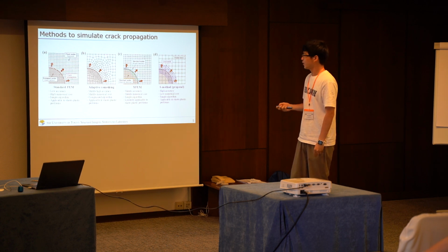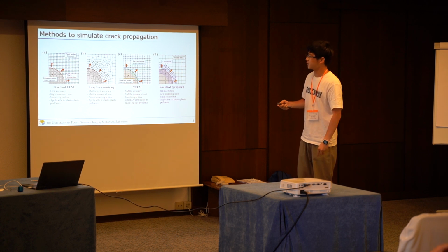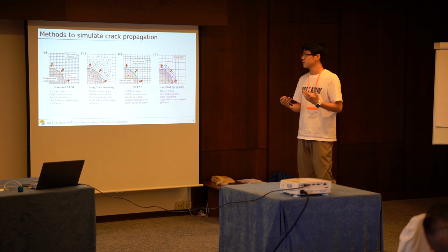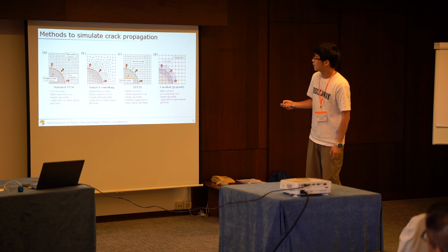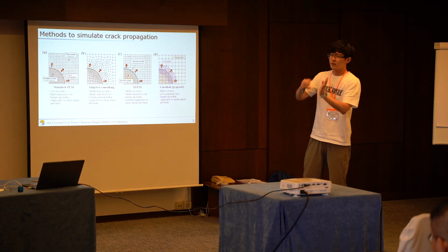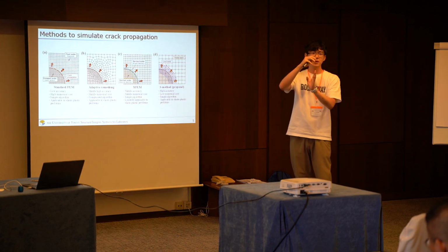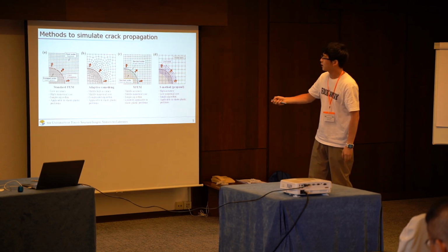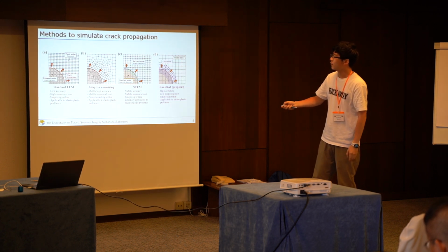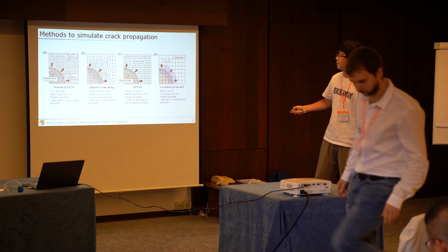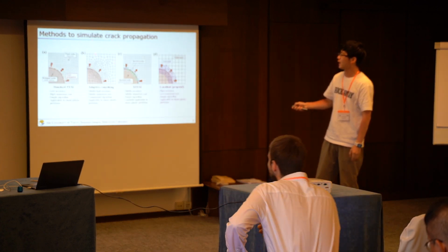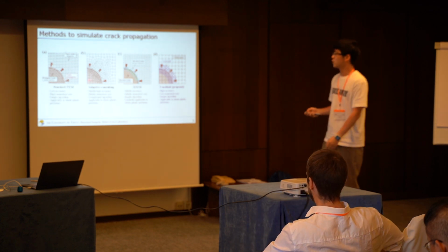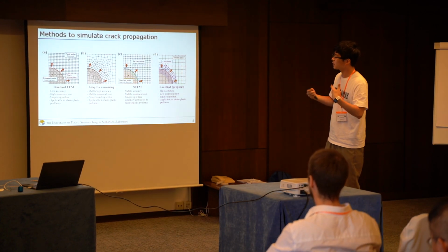accuracy. The next method is also based on the standard FEM, but with adaptive meshes. In this method, the crack front can be coincident with the element edge. Because it only applies a relatively fine mesh along the crack front, and the other parts are coarse mesh, the numerical cost is middle.